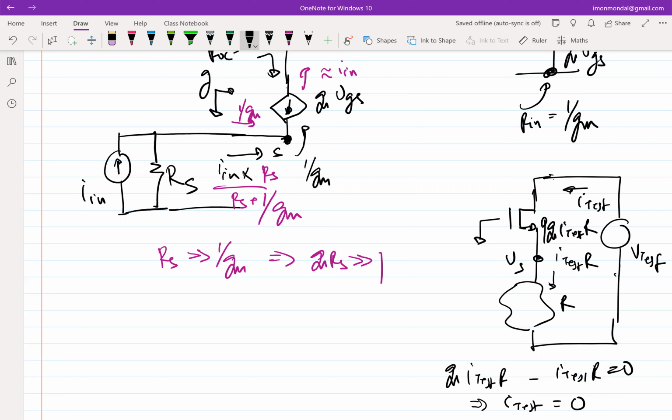Yes. It should not be surprising, because even let's assume the load is 0, which is source is grounded. Then also, what is the output impedance? Yeah, Vs is 0, but what is the impedance of the transistor looking into the drain?